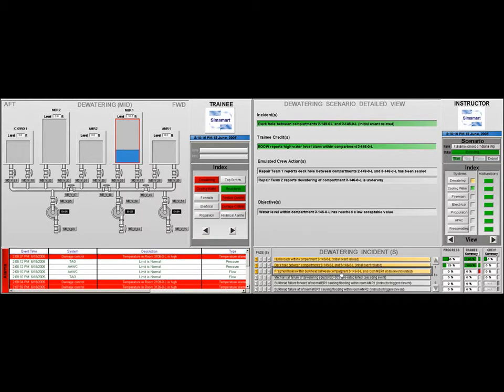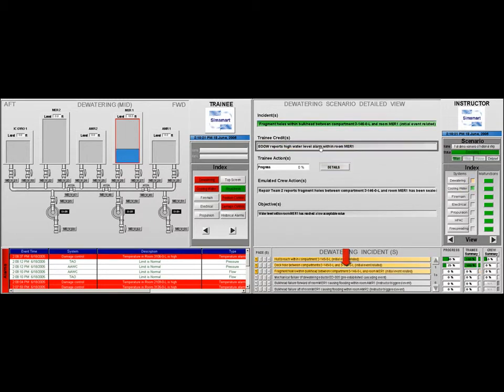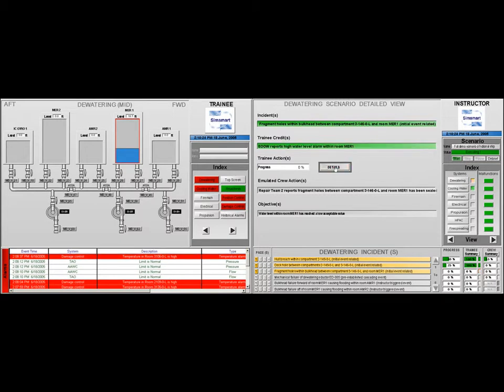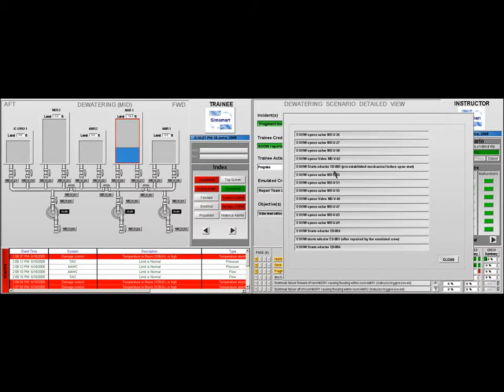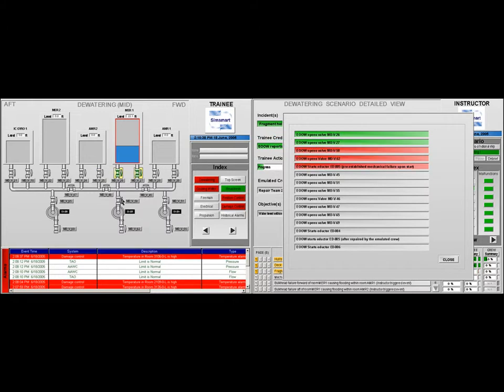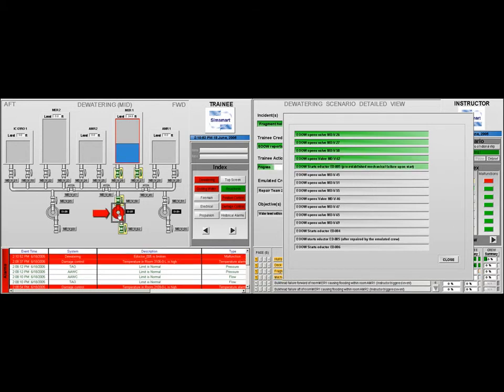Another incident line confirms a similar alarm for a different compartment. The list of precise tasks that have been done to control and contain the incident is displayed. The tasks are basically to align the dewatering line's valves and to start the eductor number 5. As the eductor number 5 is started, an LPMS cascading incident based on the start of the eductor process condition automatically fails it.